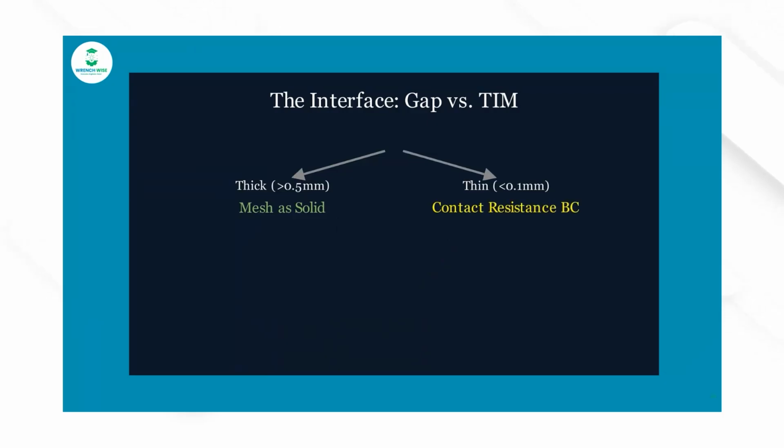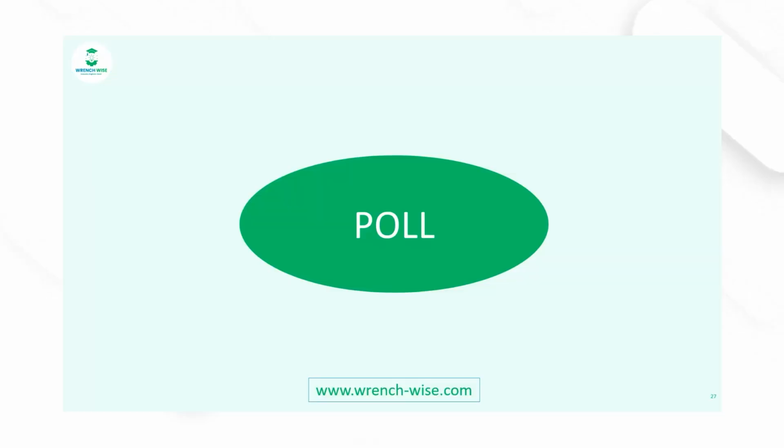If it is less than 0.1 mm, you just introduce the contact resistance boundary condition. Yep. So here the anisotropic simulation begins to diverge or shows numerical oscillations. Which setting should you use to stabilize it? Temperature gradient, mesh aspect ratio, energy relaxation factor, or copper conductivity? Yes, it is the energy relaxation factor.